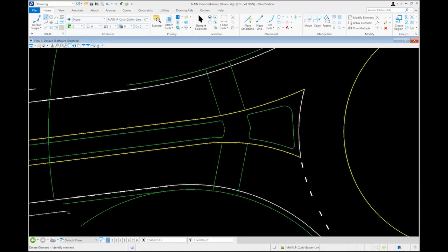For this particular location, we'll demonstrate laying in that taper and laying in that bike ramp. We want to make sure that the bike ramp is within that range that's about 100 feet away from the entrance line, but then about 50 feet back from the pedestrian crossing. So if I just give myself a quick reference line here, and come back 50 feet from the crosswalk location. So really, I want to have that bike ramp somewhere right in this area, which is going to end up being pretty ideal for tying in a taper right into this initial entrance curve.